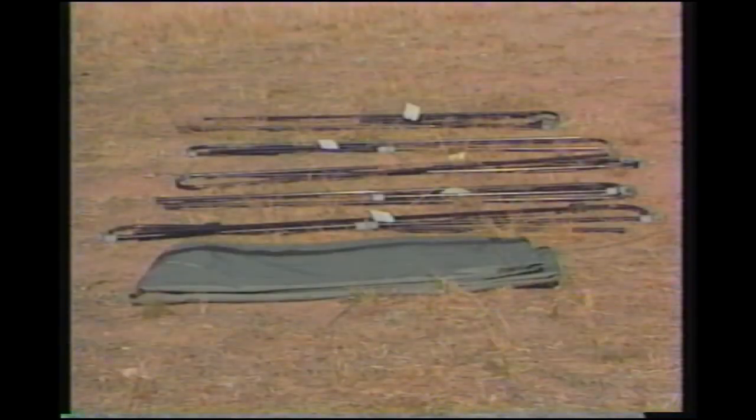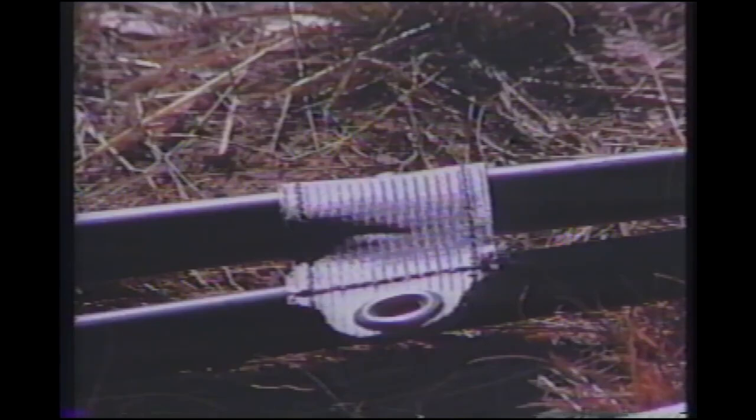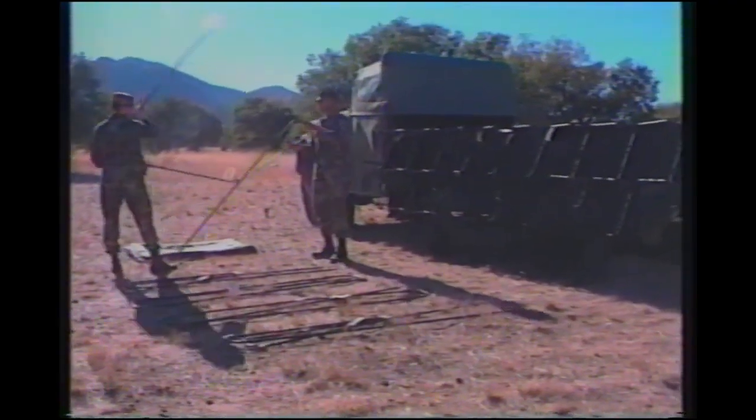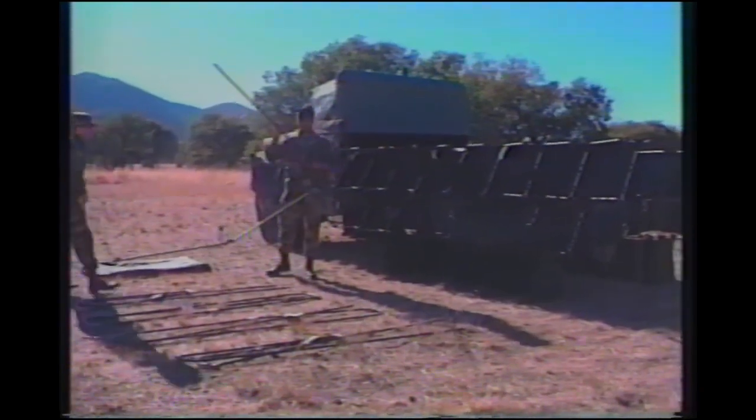The next area we will cover is the installation of the cargo compartment support bows and canvas cover. The installation of the 5 support bows will require 2 personnel for easier assembly. Installation should begin from the front with the number 1 bow being closest to the cab and the number 5 bow placed at the rear of the cargo bed. The number 1 and number 5 support bows have tabs with grommets on top of the upper sides of the bows. The other 3 support bows may be placed in any order between the number 1 and number 5 bows.